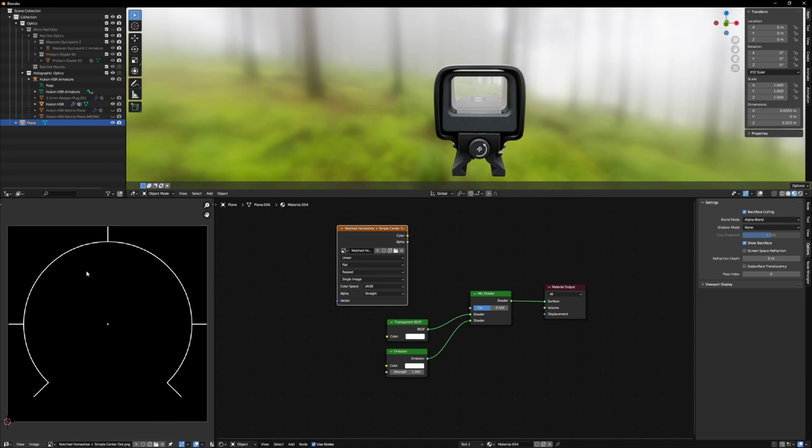Just keep in mind that larger textures use up more VRAM, so you have to weigh the benefits of the slightly higher fidelity, because are you going to notice the difference between 1000 by 1000 versus 500 by 500? Now, to be fair, both have a pretty negligible effect on VRAM usage, but if you're working in a really big scene and you need all the VRAM you can get for other stuff, it might be worth it to drop it down to 500 by 500. I find the 500 by 500 is fine for me, so you do whatever you want to do.